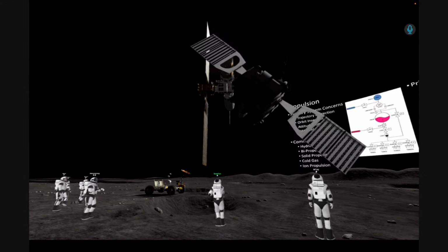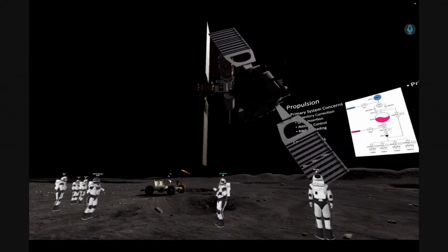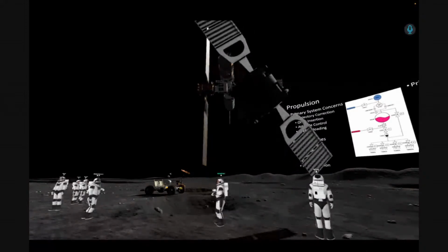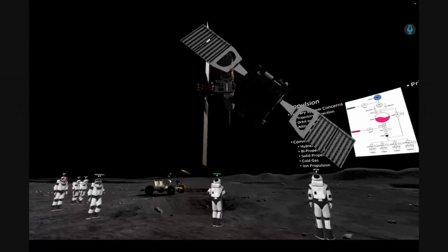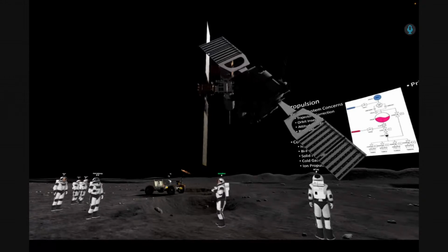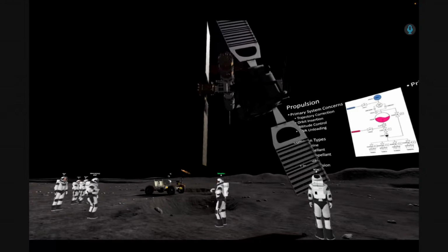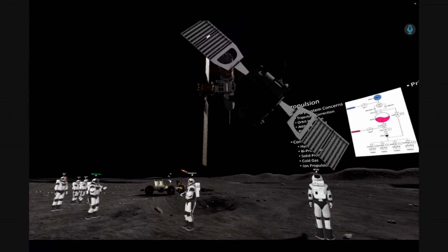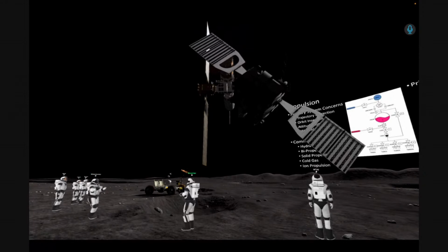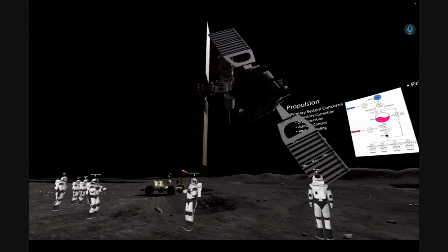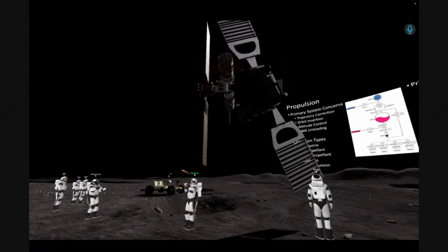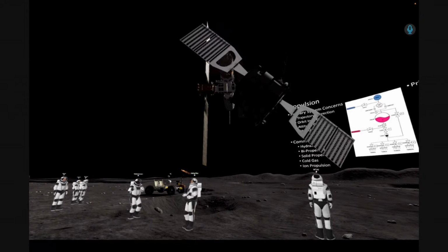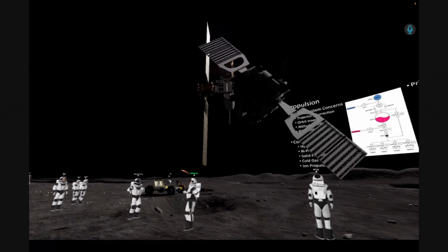So if we want to change a little bit the orbit, that is trajectory correction, but if we want to change planet, it's orbit insertion. Okay, and then we have RWA unloading, which is reaction wheel unloading, and I'm going to explain that later because it can be more complicated. But basically, sometimes in your satellites you can have little wheels, like actual wheels. I don't know if, Camilo, we have reaction wheels. There are actual wheels that can be in space. It's actually just a wheel that you put inside the satellite, and if you start accelerating this wheel, the satellite itself is going to move the other way around. So you can use that for changing the attitude of the satellite.